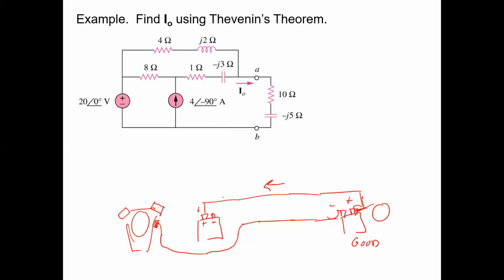They peg that pretty well. No, you're not damaging your battery by jumping. But if the other battery really malfunctioned, like it's a short, and you hook up your car to it, you could damage your alternator, which is charging your battery, because it might not be able to handle the current.